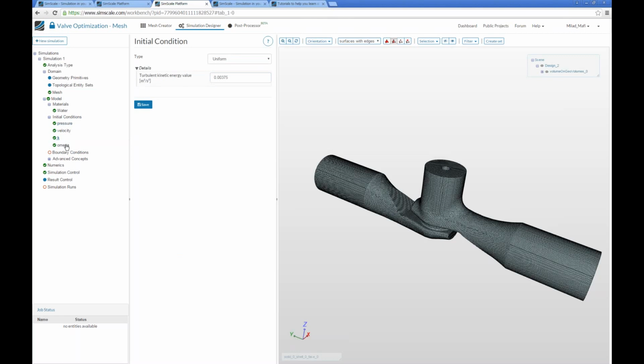The only exception is K and omega. K and omega are these so-called turbulence parameters, and they are used to describe turbulence. You can calculate them for your application using some Excel forms or online tools. It's very easy, and we just have to add them here because they are used later on, and with 0, 0, 0 it will not work. So just enter them here.